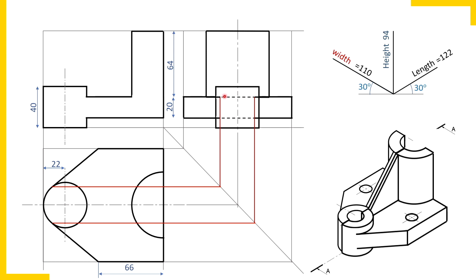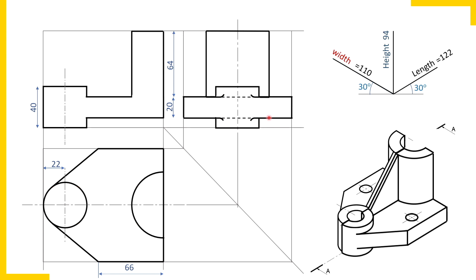And then by drawing those small curves at the end of these extensions to indicate the tangential joint. Check. So this is how we indicate the tangential joint. Now one more thing here. When there is a joint on the end generators of a cylinder, the end generator inside the joint does not appear. Okay. So watch. So this is how the left side view is complete, for this plate, of course.